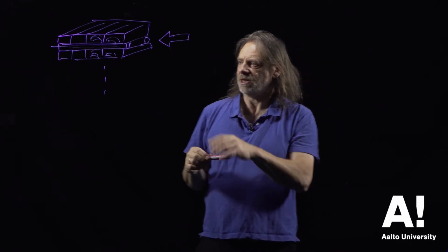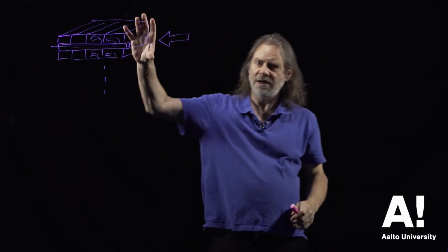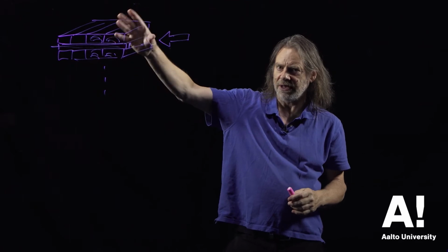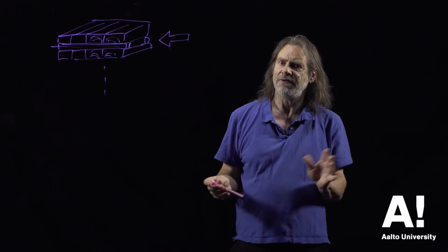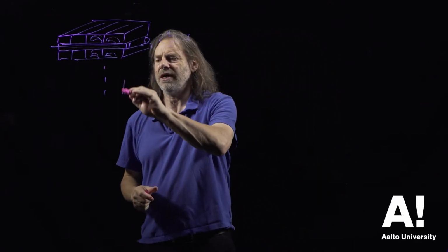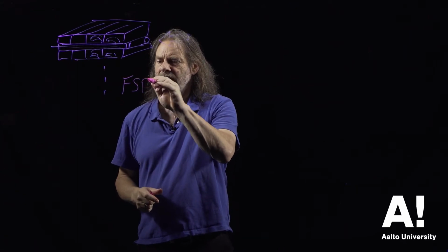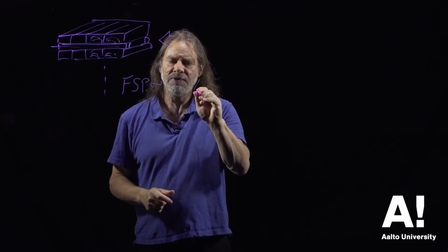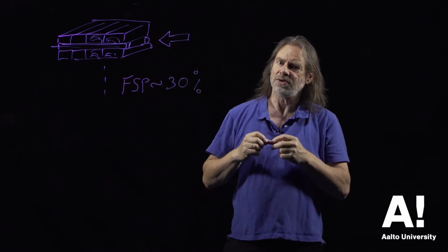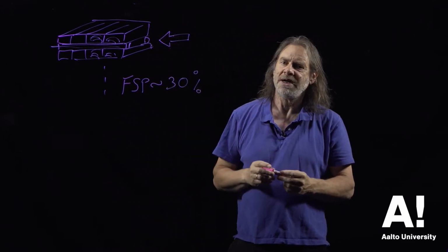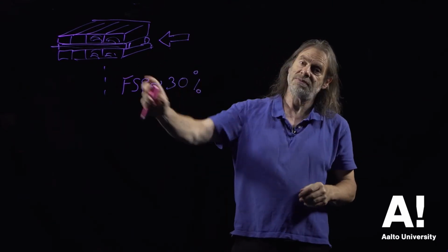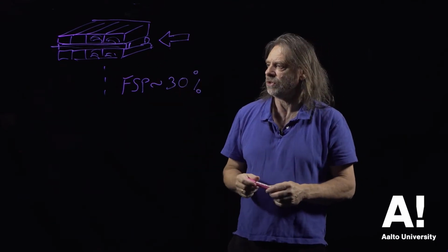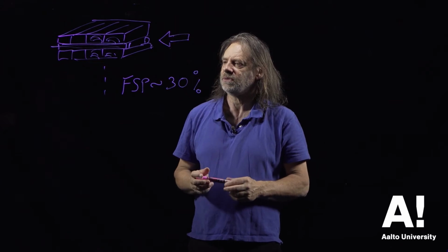Now, for quite some time, the moisture content of this wood will be at the green moisture content, and by green moisture content we mean above the fibre saturation point. And the fibre saturation point, for the purposes of this discussion, is something of the order of 30% moisture content. So that's based on the dry mass of wood. So that would be 30 grams of moisture in 100 grams of wood, a fibre saturation point of 30%.